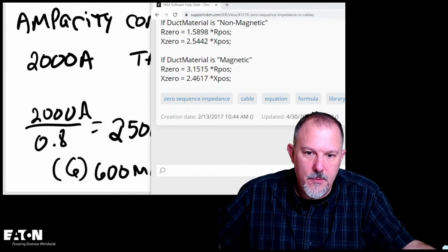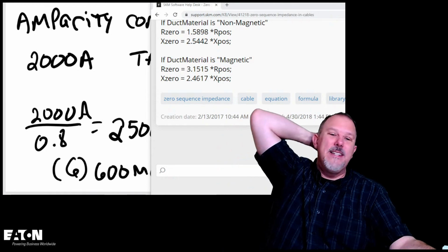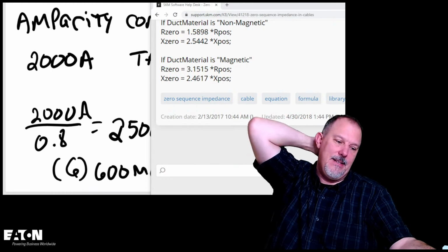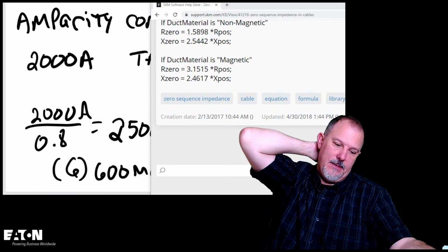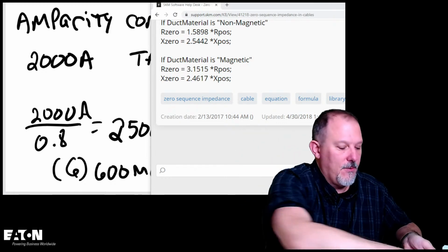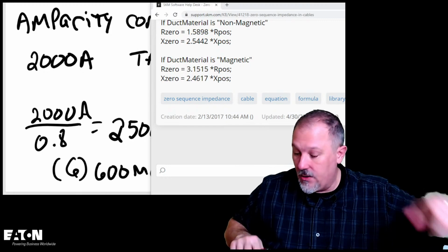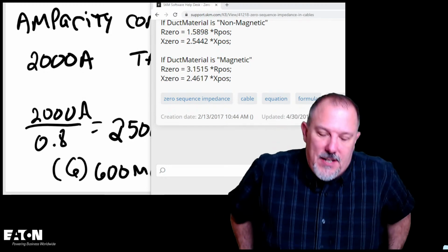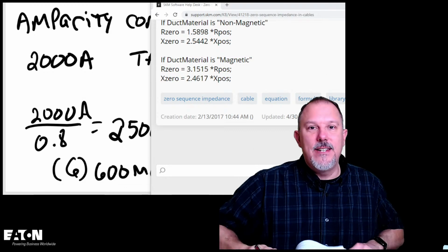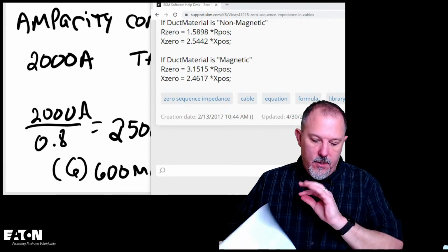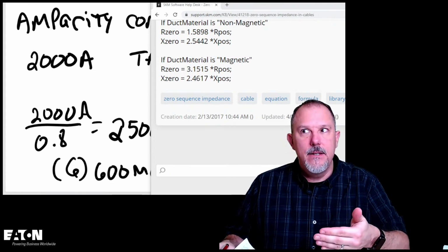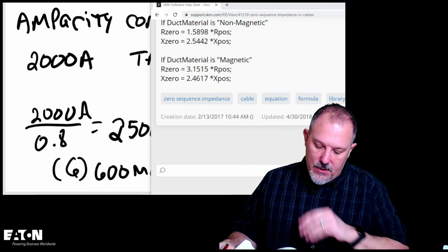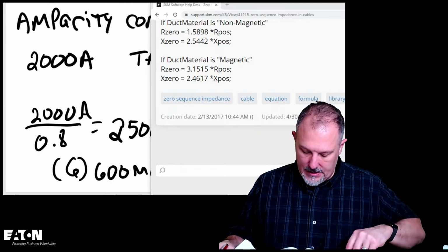Hang on, I think you were using the 75. Oh, dadgummit. Yeah, you're right, Ryan. Hold on. You're right. I was. Okay, what Ryan Jackson is pointing out is I can use the 90 C column to do my calculations, but I can't exceed that 75. So let's do the math again.